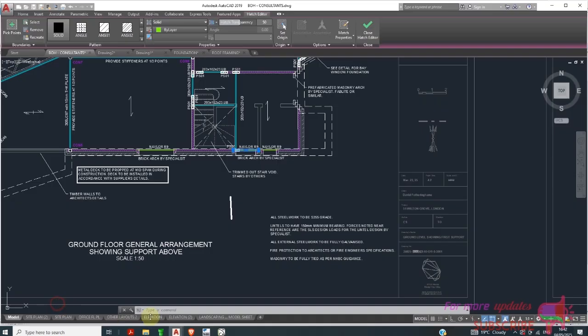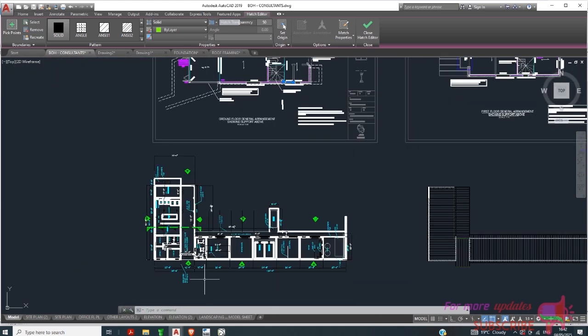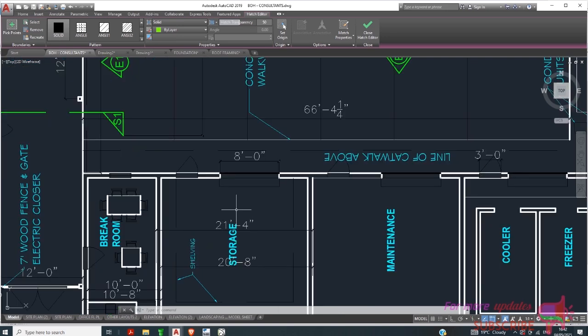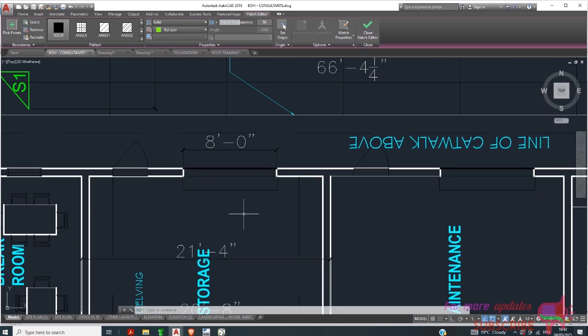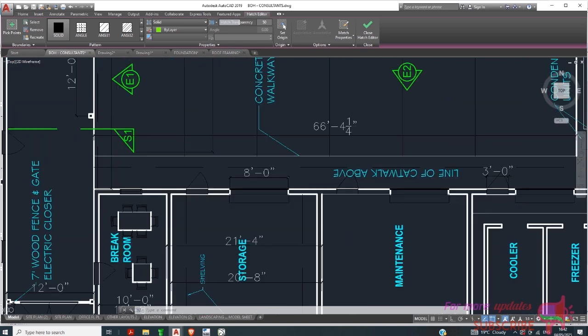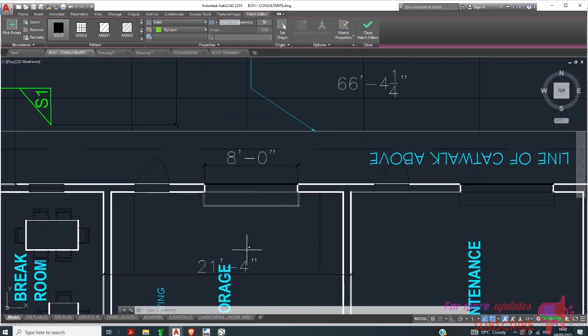Now, if you have a stud wall, when you're designing a stud wall, over the doors and windows, you need to design a header to support. For example, if you're having a floor above, you need a floor header. If you're having a roof above, you're having a roof header. The difference is that for a floor header, you will be including the floor load. But in my case, I don't have any floor on top. I only have the roof. So this one is like a roof header.